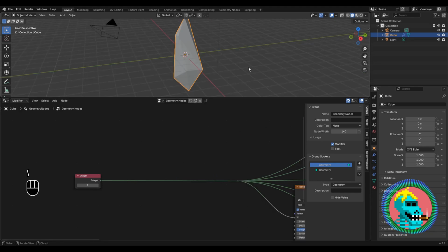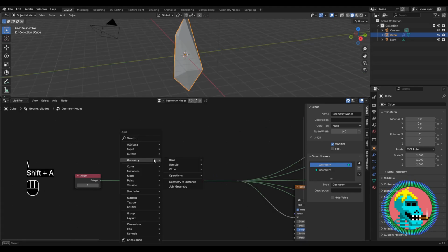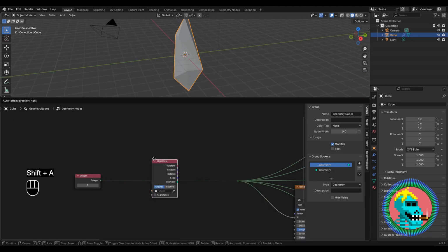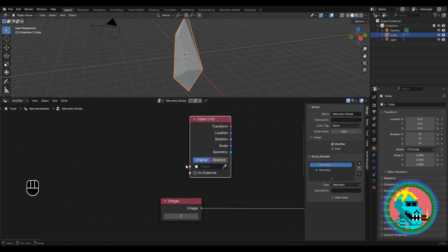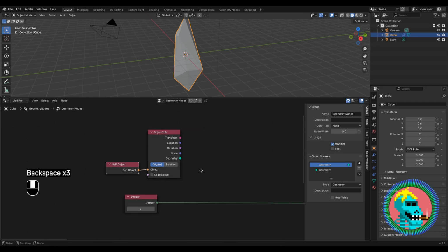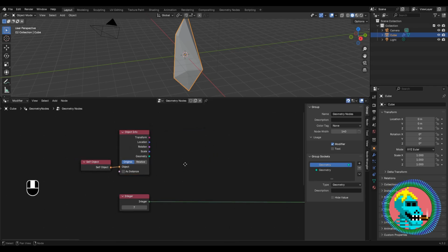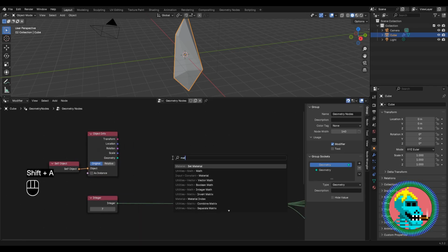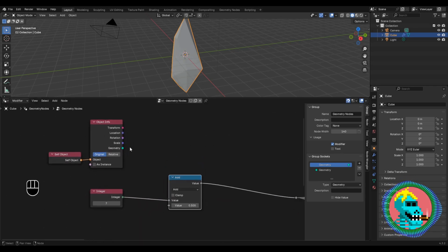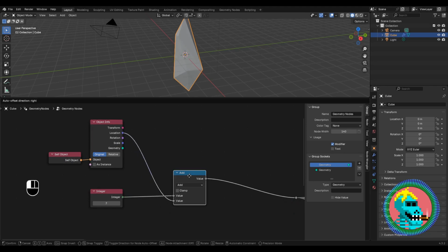And to make generating even easier, let's add an Object Info node. As the object, we'll connect a Self-Object node. And we use the location as a multiplier. In this way we get an infinite number of new generations depending on the location.